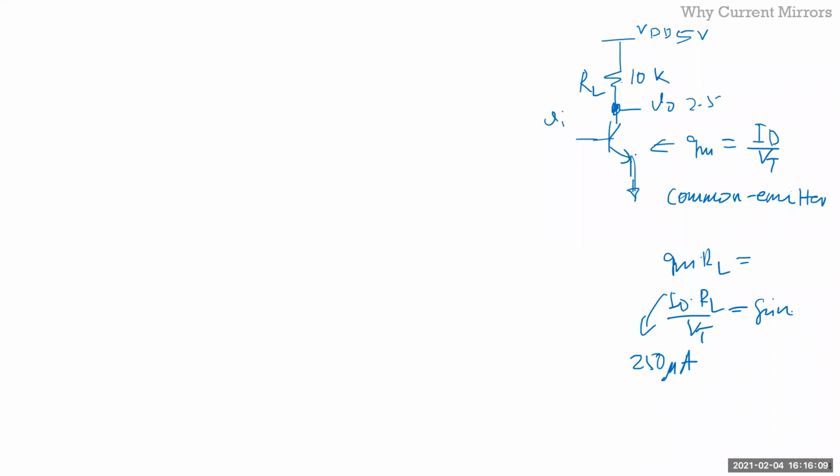Now, how do I force 250 microamps here? I mean, you can apply a gate voltage and tweak it ever so slowly. When it's exactly 250 microamps, you stop. But then the temperature goes up a little bit, and the output is just railed. Then somebody comes in and tweaks it, and then it's gone. So that's not a good way to bias it.